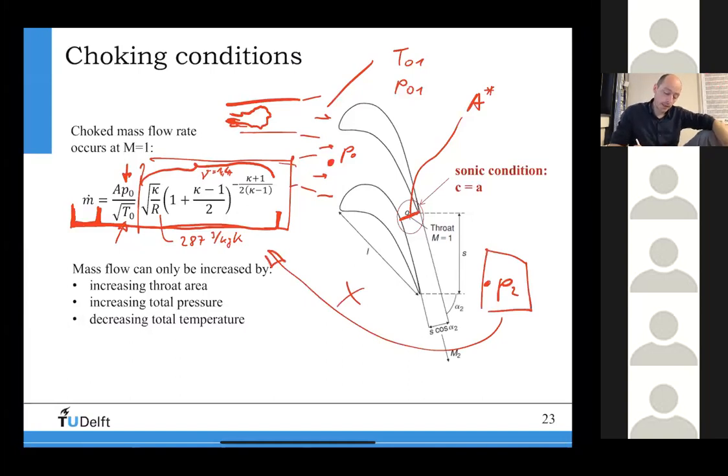So, which means that if you have a well-defined pressure in the combustion chamber given by the compressor, and if you add the right amount of fuel in the combustion chamber, you can control the temperature. And by controlling these two parameters, you basically control the whole mass flow through the gas turbine. It is controlled by this area here.